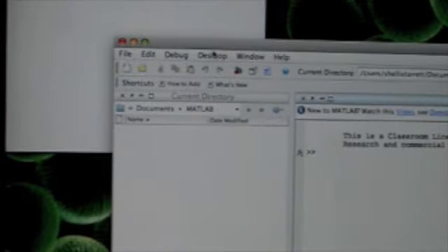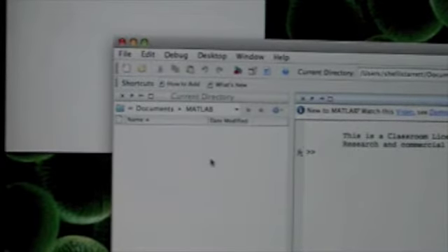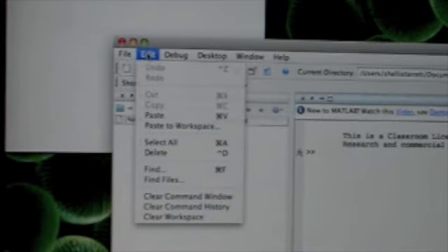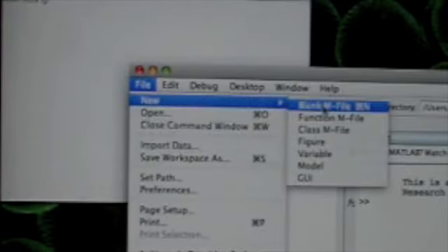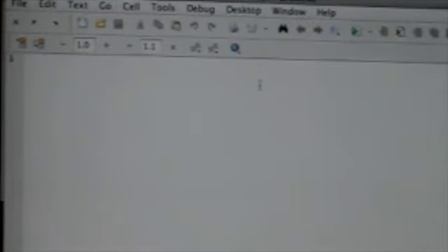Okay, let's try a little bit with Matlab here. I've started up Matlab on my computer. This is a Macintosh version. I'm not sure how others will be different exactly, but I wanted to talk a little bit about making an M file. So here I would go to New, Blank M file. Okay, so it brings up the editor.